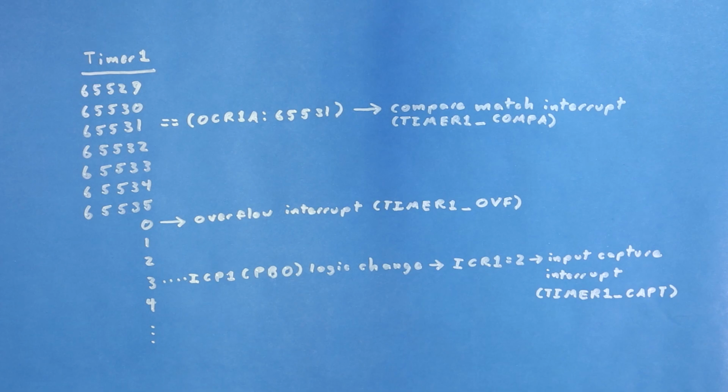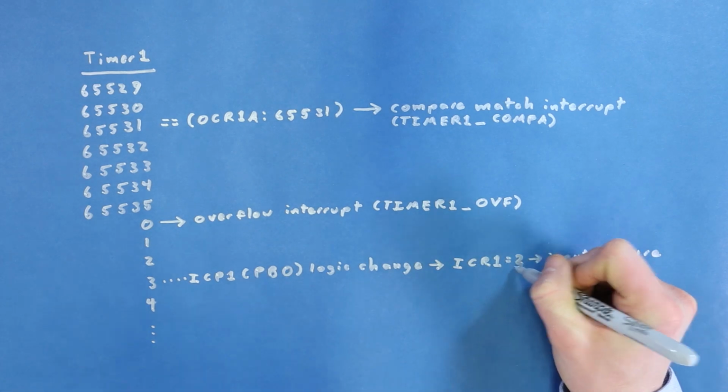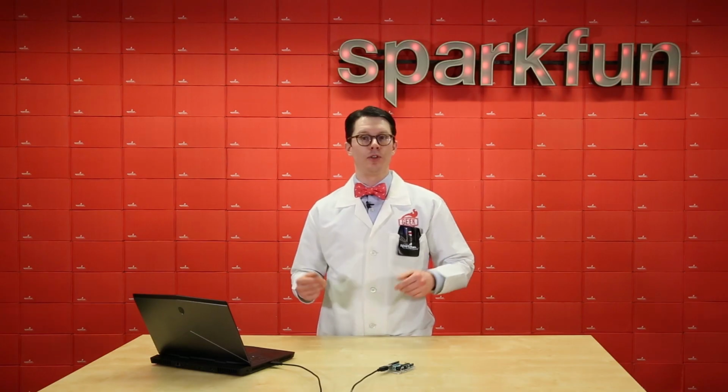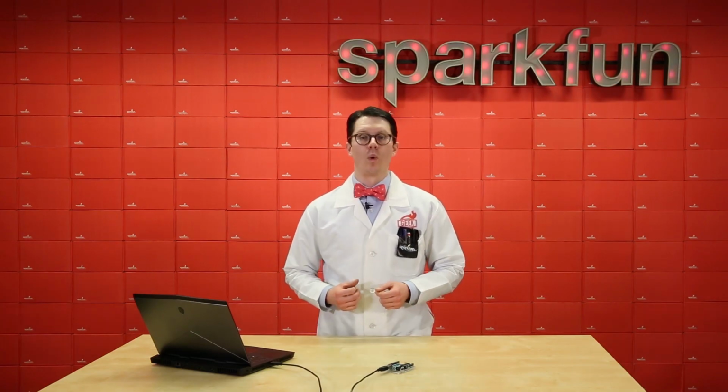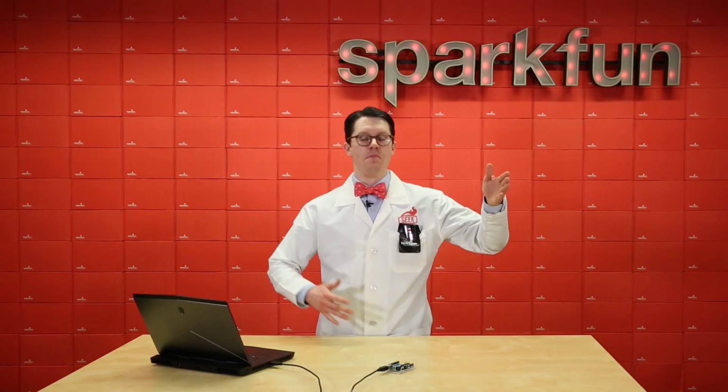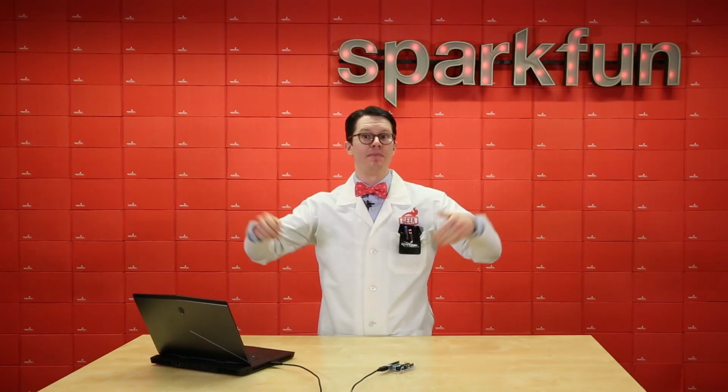At the same time, the value of the timer 1 counter is stored in the ICR1 register, so you can refer to it later if you want to see exactly when that event occurred. Compare and overflow interrupts are useful if you want to, say, toggle a pin or read from a sensor at precise regular intervals. Capture interrupts are great if you need to measure the time between pulses or measure the frequency